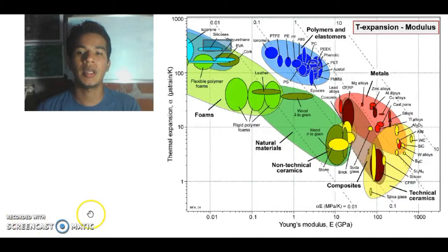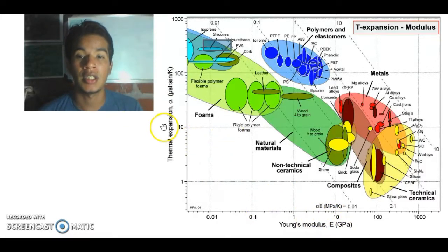Good afternoon. The Ashby method is based on graphs of material maps in which certain properties of the material are related in pairs. The method was designed exclusively to be used during the conceptual stage of material selection. The expansion modulus chart: linear thermal expansion alpha against Young's modulus E. The chart is used in material selection.